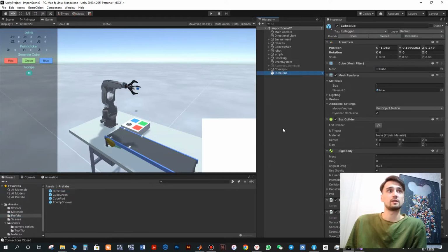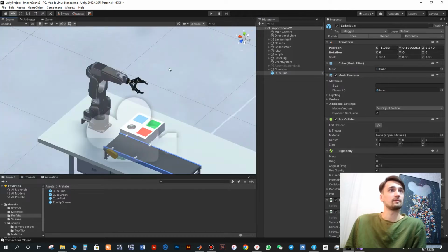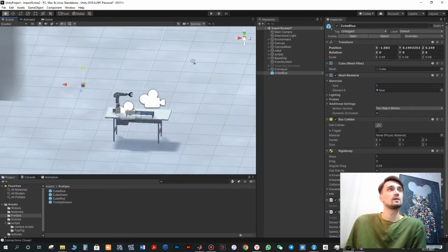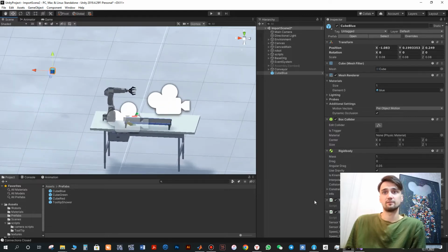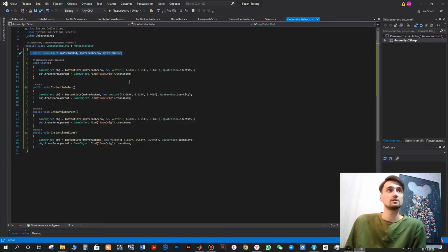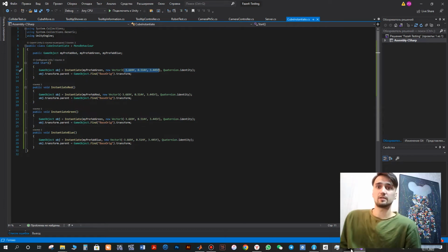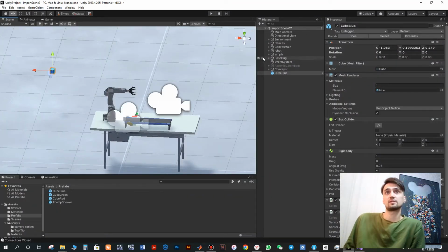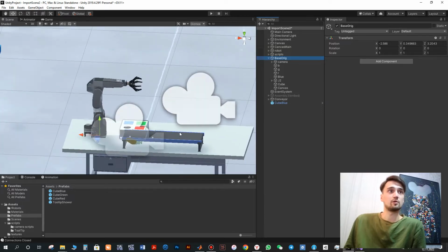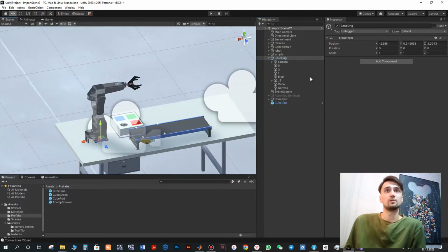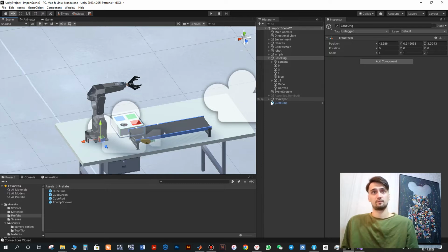So if we put it here, it will be instantiated somewhere in space. We want to give it some other coordinates to put it above the conveyor. So we firstly specify where we want to locate our cube. Next, as we make reference to our region, we need to put it to our base origin, to our robot origin. So the robot will know where our cube is.